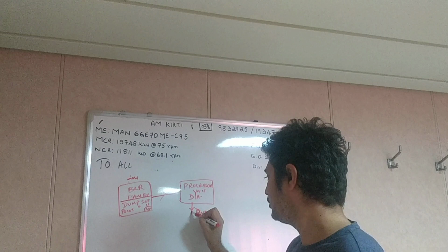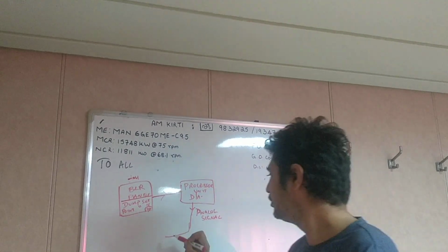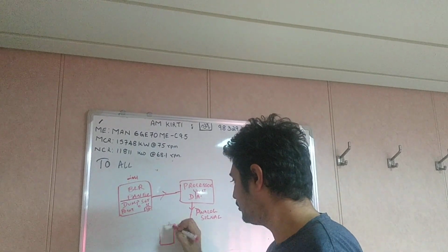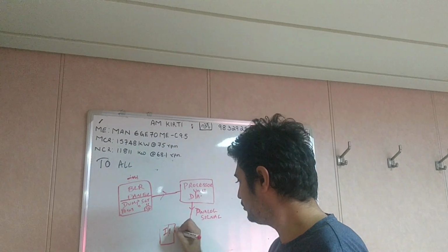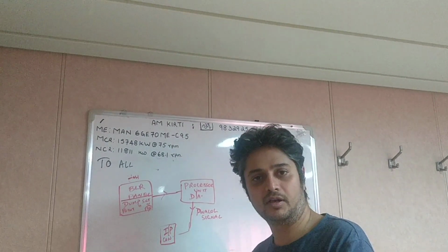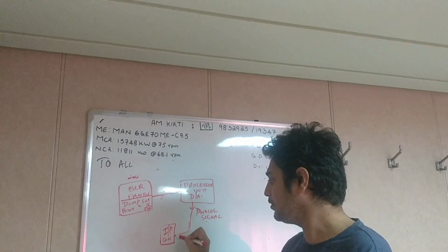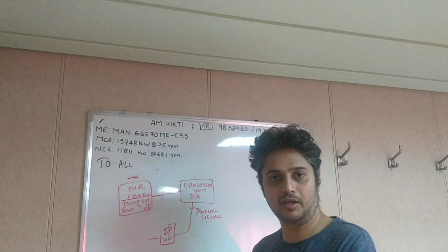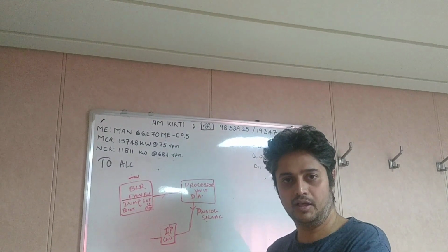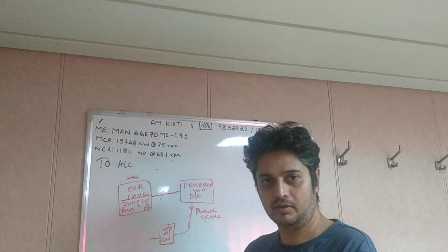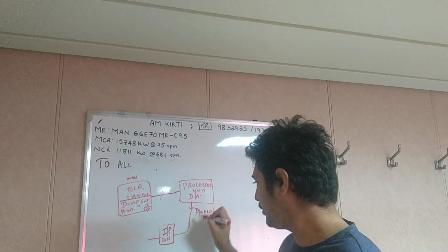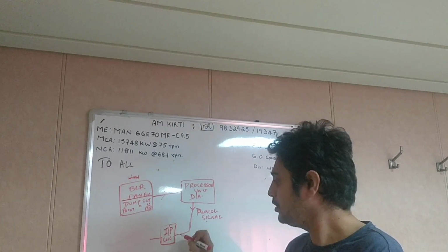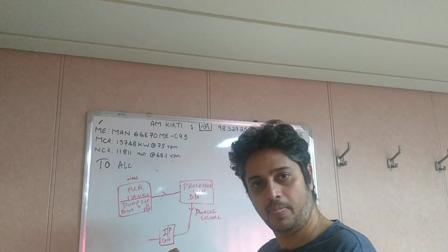Okay, from here it goes to the IP converter. What the IP converter does is, whatever analog signal it is receiving, it converts to the corresponding pneumatic signal. It will have a pneumatic supply, a controlled pneumatic service air supply, and you will have a reducer and orifice and all. As per the analog current signal which you are getting, it accordingly gives a pneumatic signal; this is what we call IP converters.